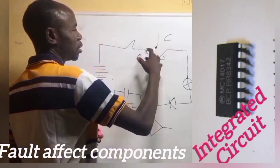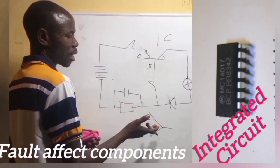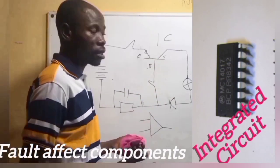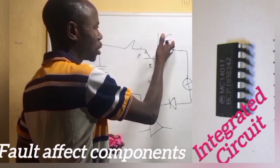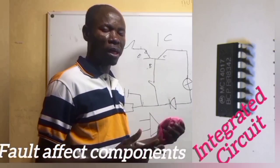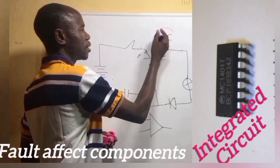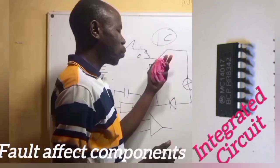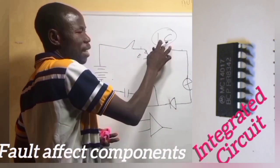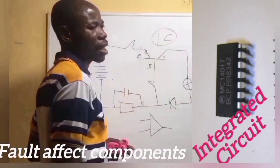As a fault, the IC can be short circuit because there's a resistor inside, a diode inside, a transistor inside. So if one of them becomes short circuit, it will affect the terminals or the reading of the IC, and it will not work well. So the faults that affect an IC are short circuit, open circuit, and increase or decrease in resistance, because all these components can be inside the IC. So the faults that affect the component are the same faults that appear in the IC.